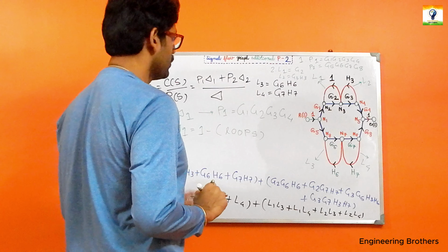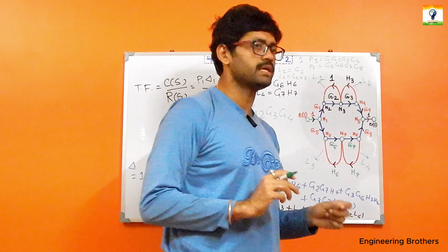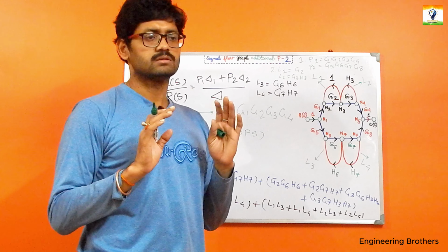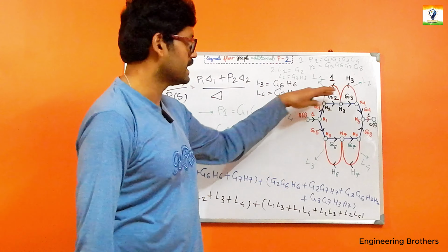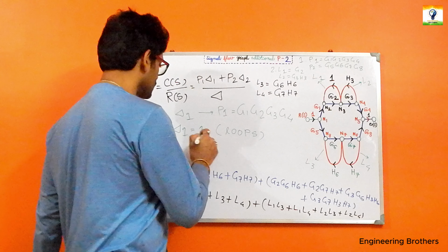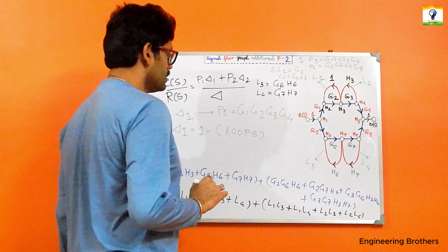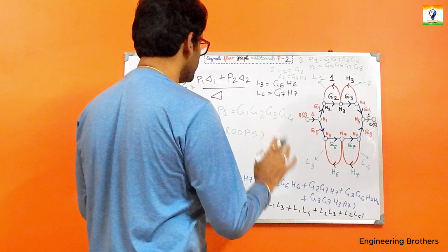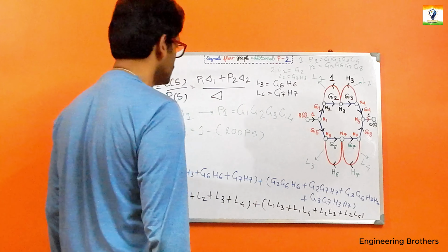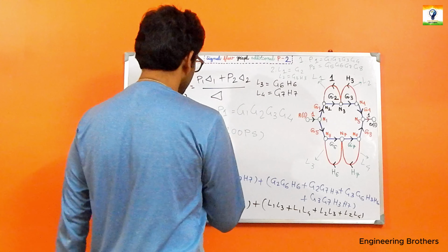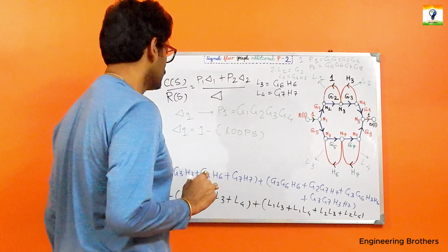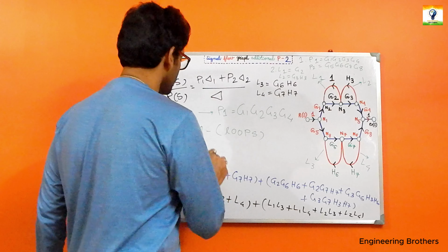If the forward path is touching the given loop, then the delta 1 expression will be 1. But if any loop is present that is not directly touching that forward path, then the expression for delta 1 will be 1 minus that loop.